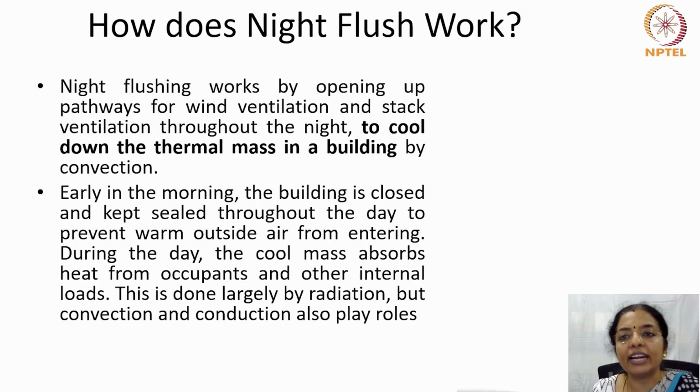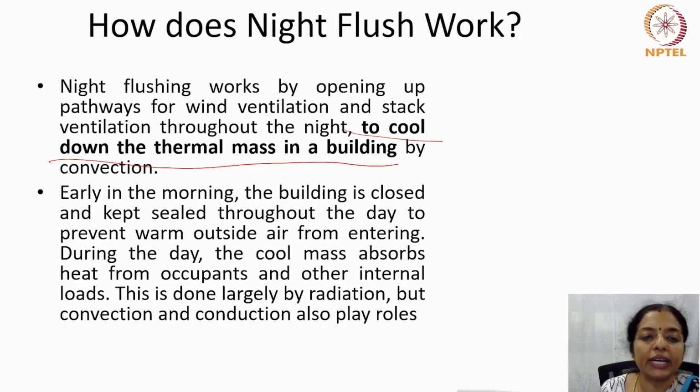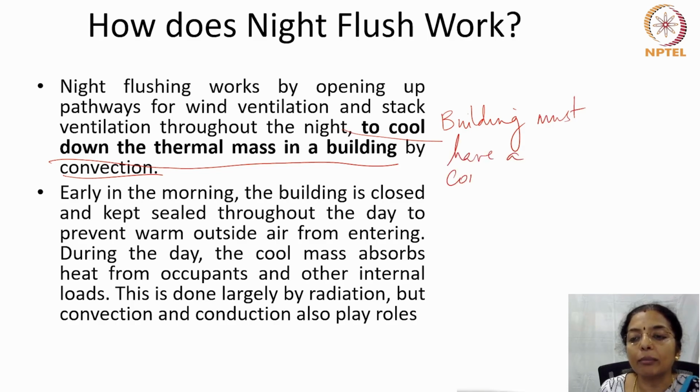So how does night flush work? Night flushing works by opening up pathways for wind ventilation and stack ventilation throughout the night to cool down the thermal mass of the building by convection, which means the building must have considerable thermal mass. Only then will this technique be effective.